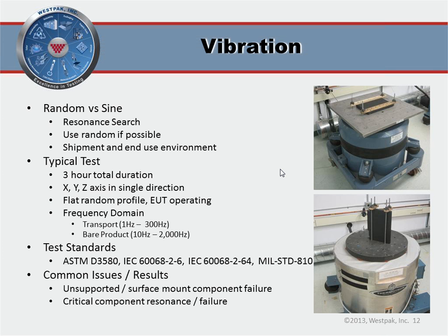It's just as easy to find resonance. In fact, the resonant frequencies that you find during that process typically are better in terms of their amplitude. The resonant frequency would be the same. But when you use random vibration, typical spring mass systems, which is really what we're talking about, respond in a way where you have constructive and destructive interferences typically on either side of the natural frequency of a component. Those will be taken into account when you excite the product with random vibration. Sinusoidal ignores that, so you might have exaggerated results using sinusoidal. Not necessarily bad, because it's easy to identify them, but certainly not as realistic as random. So that's what we recommend.